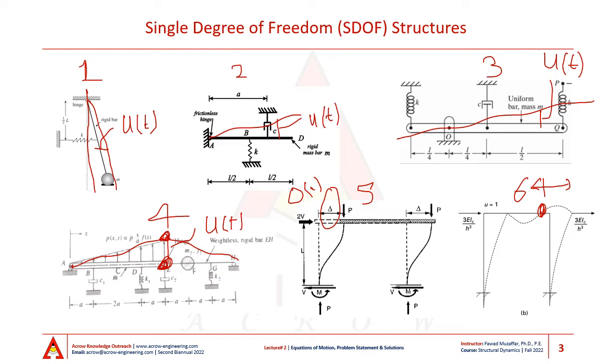Whereas, as far as the stiffness of the frame is concerned, we have to have two rotational components and one translational component to completely describe the stiffness of this frame element.